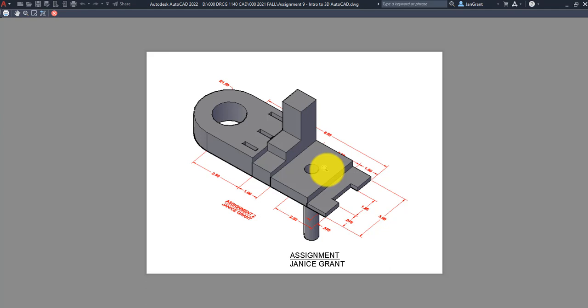But what I wanted to say is that if you see your viewport box right there, don't print it. Don't hand it in, right? You want to make sure that that viewport box is on a layer that won't print. So create that viewport layer, make it a no plot layer, and make sure that that box is on that layer. The other thing that happens sometimes is students will not switch their layer around, right? And the assignment name will still be on the viewport layer. So if you don't see that, it could be there.